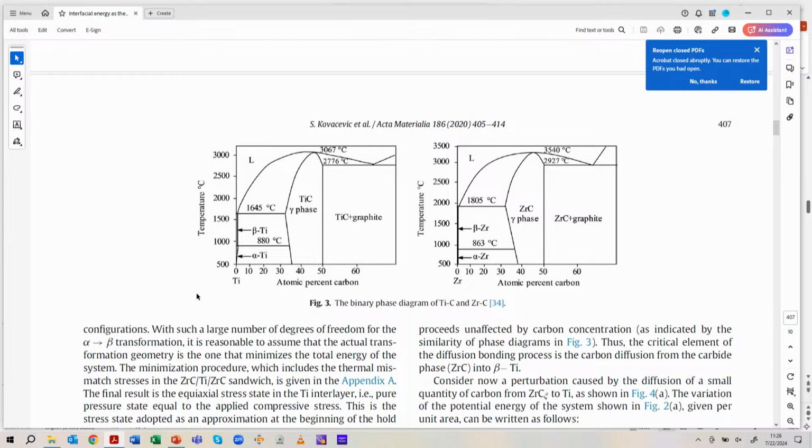That is like two FCC lattices, let's say FCC zirconium and then carbon FCC interpenetrating. Or you can treat it as one lattice, B1 structure, or two interpenetrating lattices of FCC type. So that's gamma phase, and we're really not going anywhere beyond this.